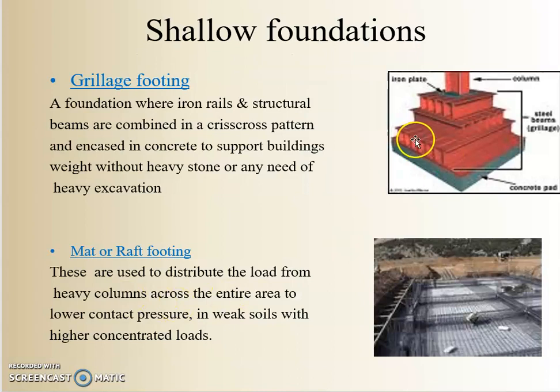Then the other type of shallow foundations that we have are grillage foundations, wherein you have a network of I sections or other built-up sections of steel. Okay, and then the next one is mat. Now, a mat or raft foundation comes under shallow foundation. The reason being the fundamental thumb rule for defining a shallow foundation is that the width of the foundation has to be larger than the depth. Obviously, mat foundations are huge foundations, so they will definitely be under the shallow foundation category.